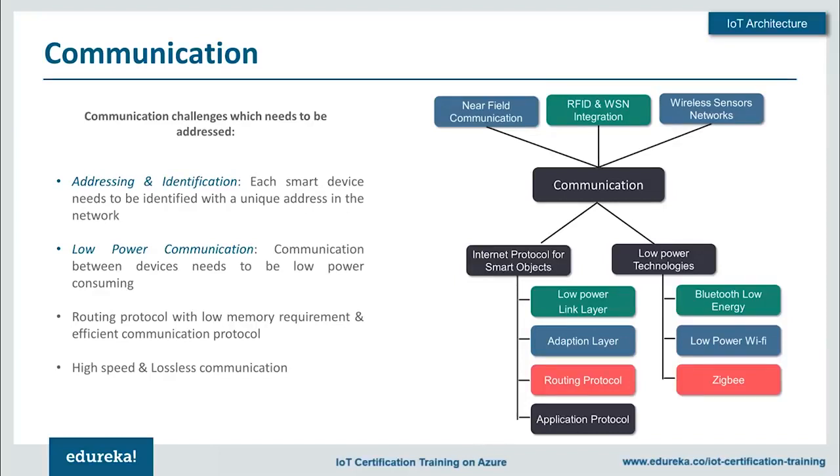So they cannot be used in many applications wherein a large area needs to be monitored through many sensor nodes deployed in various locations. A WSN, or wireless sensor network, consists of 10 to 1000 sensor nodes connected using a wireless technology. They collect data about the environment, communicate it to the gateway device, and relay the information to the cloud infrastructure over the internet.